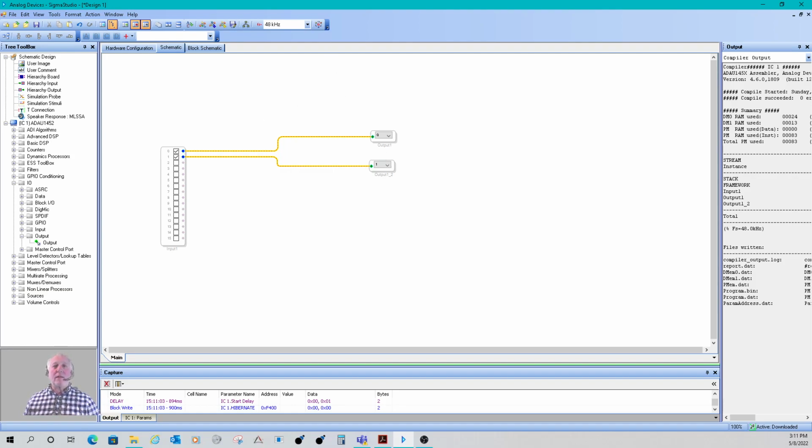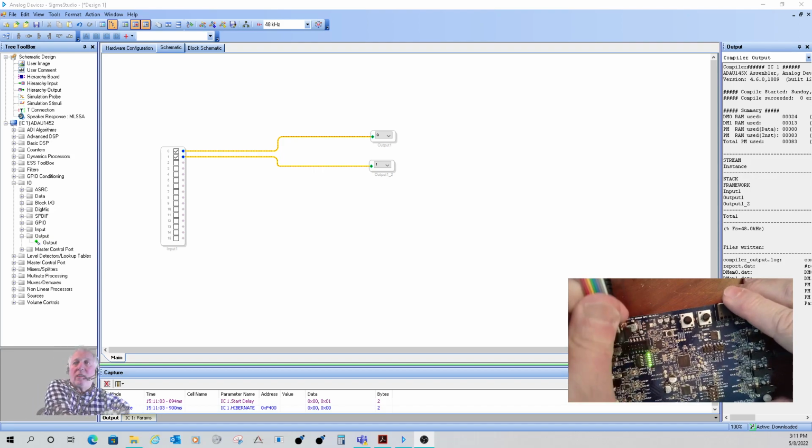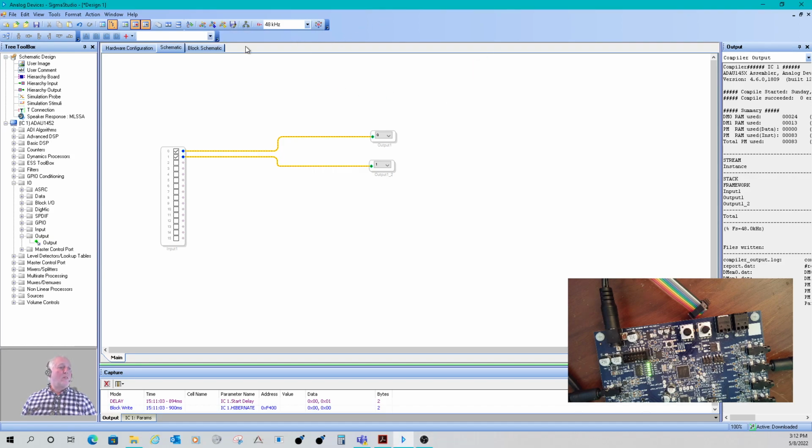Let me turn on that other camera and I'll show you a perfect example here. I'm going to disconnect my communications, so I'm obviously not communicating with the part. And I'm going to go link compile download. Actually, I'm going to hit reset first because the program was still running in there and we would have heard audio. Now link compile download. Everything compiles because it's SPI, it's not I2C. It has no idea there's no eval board listening. It's talking, nobody's listening. Now I hit sound and I hear nothing.